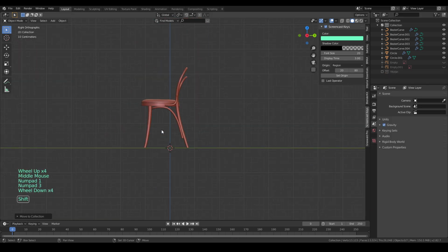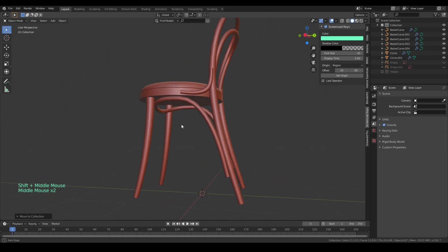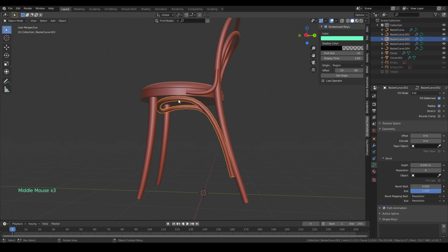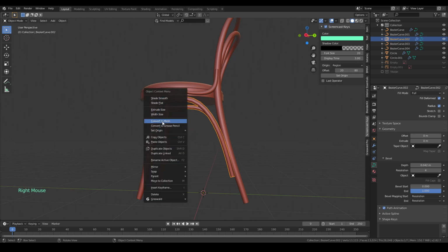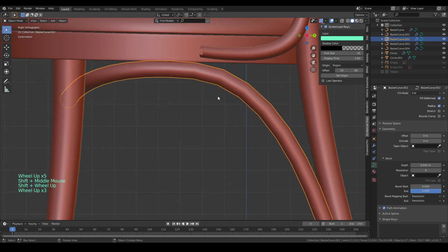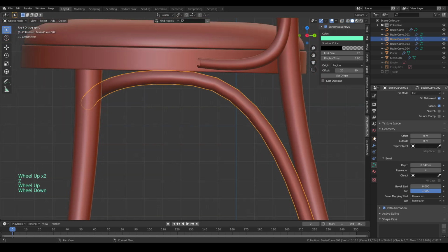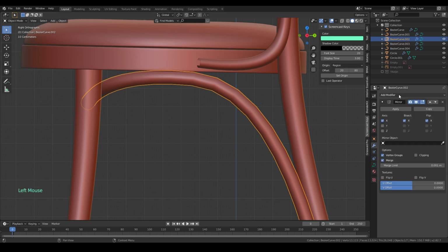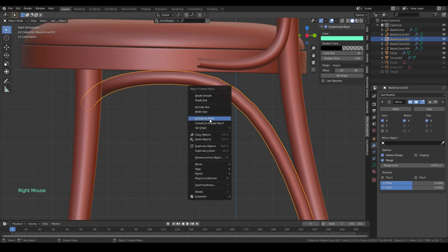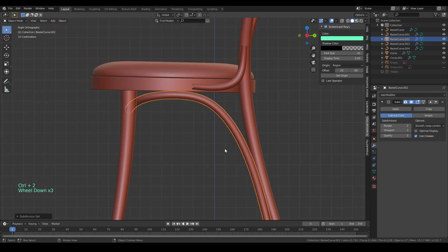So the rest is just the curve. So I just make a backup. Okay, I right click and choose convert to mesh. And before I convert to mesh, I wanna double check the wireframe. So the wireframe is not too low, but it's not too high. It shouldn't be too slow. So I'm gonna convert to mesh and add a subdivision to see if it's smooth enough.